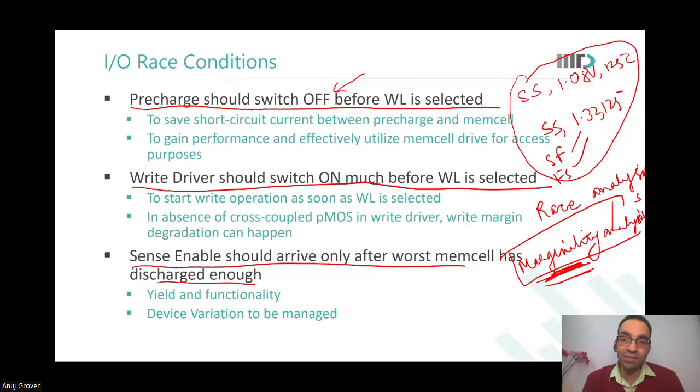When you actually do memory analysis, you will notice that there are more than 30 conditions. Yes, you can write 30 different test vectors and run each on only one PVT. You can do that. Yes, sir. No problems. But I prefer to say there is no harm in measuring the margin even on a PVT where it is not critical. I would rather measure everything, but reduce my work.